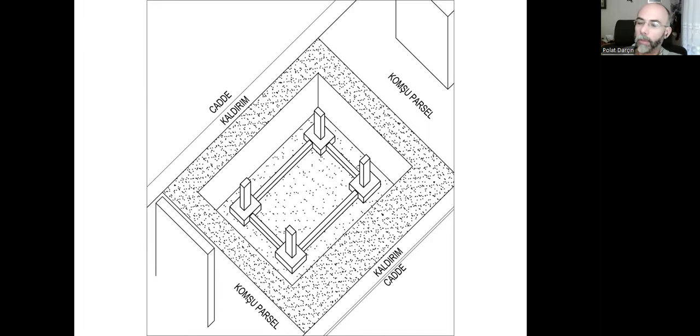And based on the properties of the ground, the grains, we can change the type of the foundation and create something stronger. If we keep continuing one of the footings towards a certain direction, we will have a continuous footing. That can be imagined as one long footing, and there will be two or more columns above this footing. So we can have a continuous footing in one direction. That's what we call a one-way continuous footing.